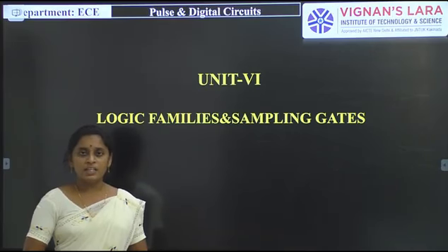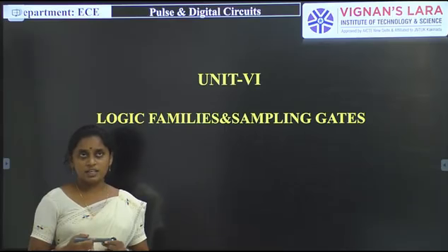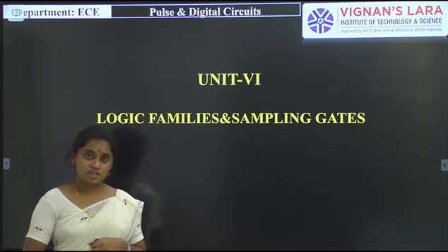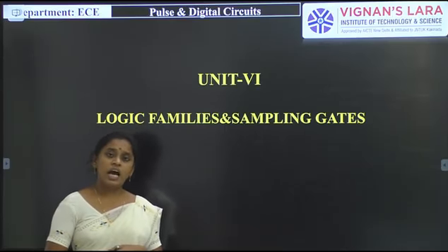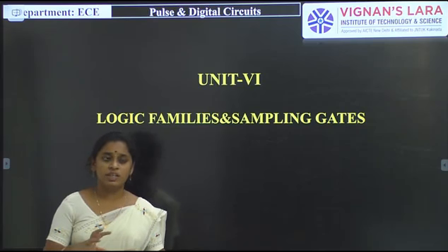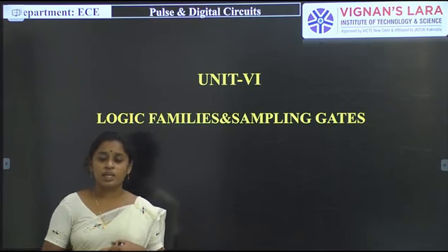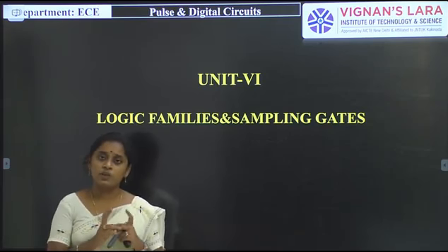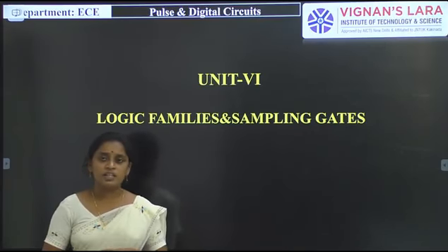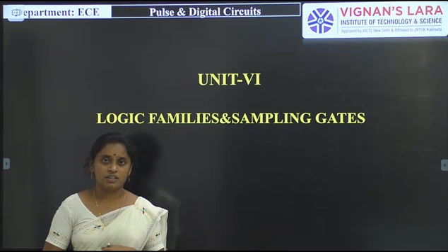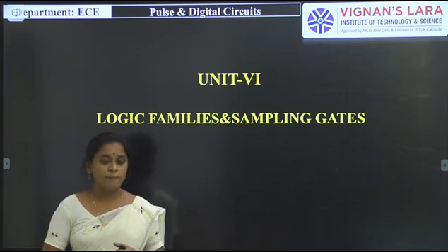At the same time, there is a chance of pedestal. Pedestal is nothing but an unwanted signal. When the control signal is applied, whatever the input signal we get appears at the output, and in the remaining condition the output will be 0, which is the actual condition of the sampling gate. But here, pedestal will occur. So this problem can be overcome by using the 2 diode sampling gate.